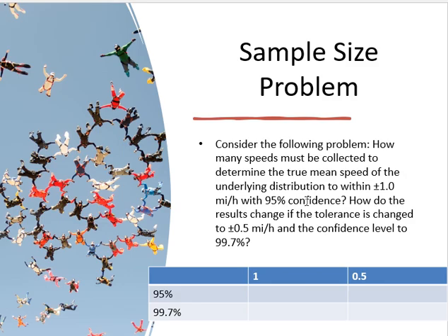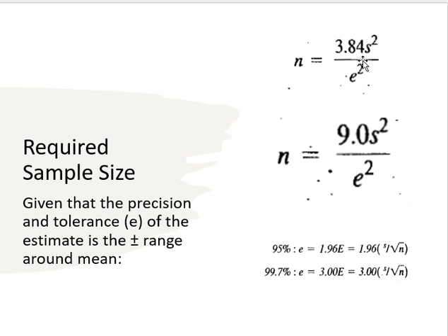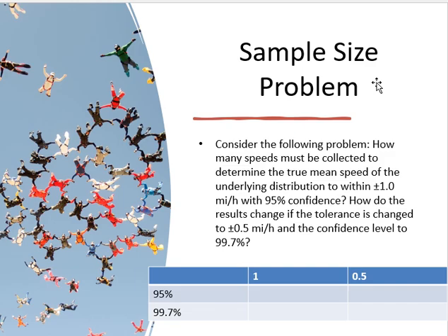Now the one thing which is missing in this question is a standard deviation. So they say that if the standard deviation is not given, then an appropriate value for standard deviation of spot speed is 5. So I can take standard deviation as 5. It's an assumption. If you have the data, then we will not assume, and then we should use the value which we have. Okay, so using these values, these are the results I am getting.